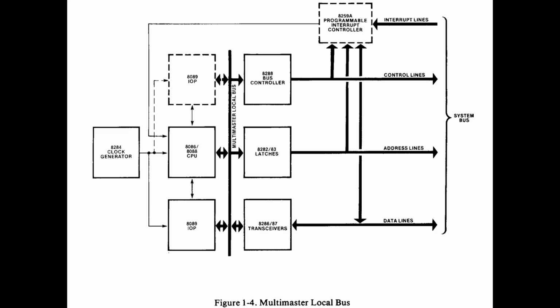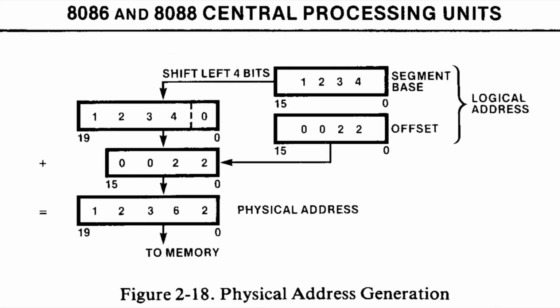The most famous one is, of course, the FPU, so the 8087, but in fact it was not important for the personal computer, so the IBM Personal Computer, because most of the programs were not programmed in a way to utilize it. The 8086 had 20-bit address bus, and they used segmentation.